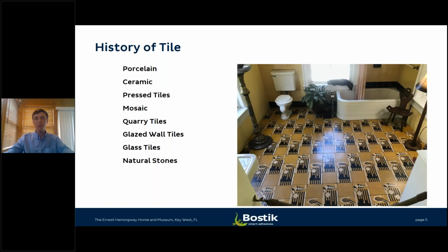People are pretty aware of the different types of tiles that exist in the marketplace. The porcelains, which are such a vast majority of the market these days, are also known as impervious tiles, or in some cases impervious ceramic. So you can even call porcelain a subset of ceramic. Then you have the ceramic category, a very broad name covering vitreous, semi-vitreous, and non-vitreous tiles, which essentially refer to the level of absorption from product to product.